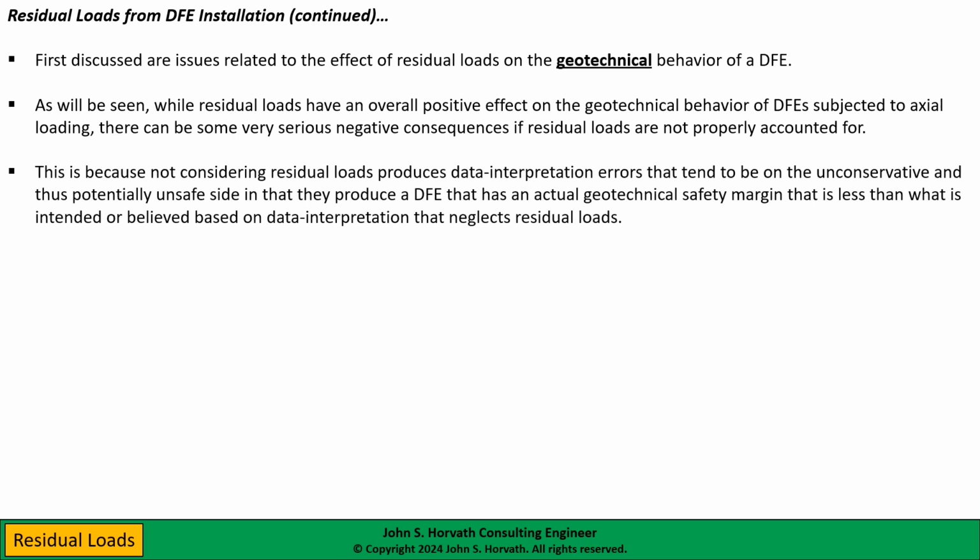This is because not considering residual loads produces data interpretation errors that tend to be on the unconservative and therefore potentially unsafe side, in that they produce a DFE that has an actual geotechnical safety margin that is less than what is either intended or believed based on data interpretation that neglects residual loads.